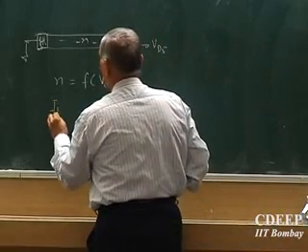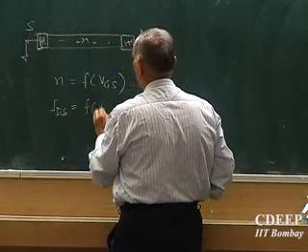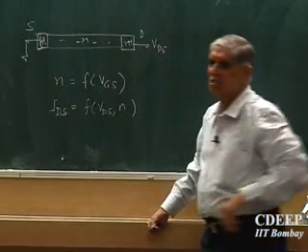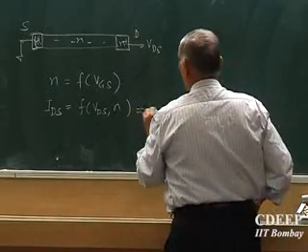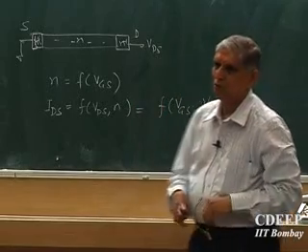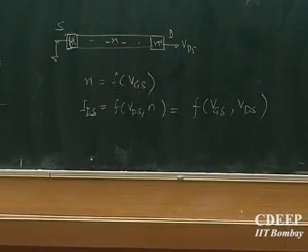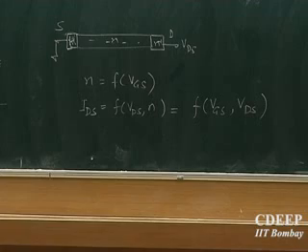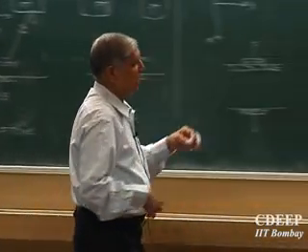Whereas the current, I call it R drain to source, if this is my drain and this is my source, is a function of VDS, and what is the conductivity I get here? Is that correct? Or to say, IDS is not only a function of VDS but also a function of VGS. So gate voltage as well as drain to source voltage both control the current. In the case of PN junction, we said only I this way or this way, nothing like this. Here that third one is now coming into the picture. So this is what we are really looking into.